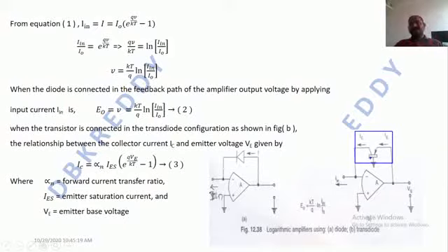What is the use? The transistor is giving the proper characteristics for a long period of time compared to the diode. That's why I'm converting the transistor into the diode format by shorting the base and collector terminal.